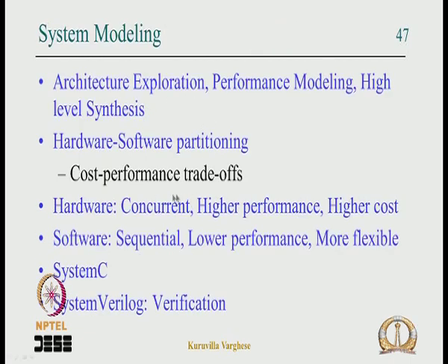This is another area as far as embedded systems are concerned, also when system on chip is considered at a top level: you need something called system modeling. When you start with a system on chip, you are not sure what part should be in hardware and what part should be in software. Many a time the hardware design is done in HDL and software design is done in C or C++, and it is very cumbersome: once a partition is made, the hardware designers start designing the hardware, the software designers start designing the software, and halfway you realize some software part has to be moved to the hardware. It is a very tough thing.